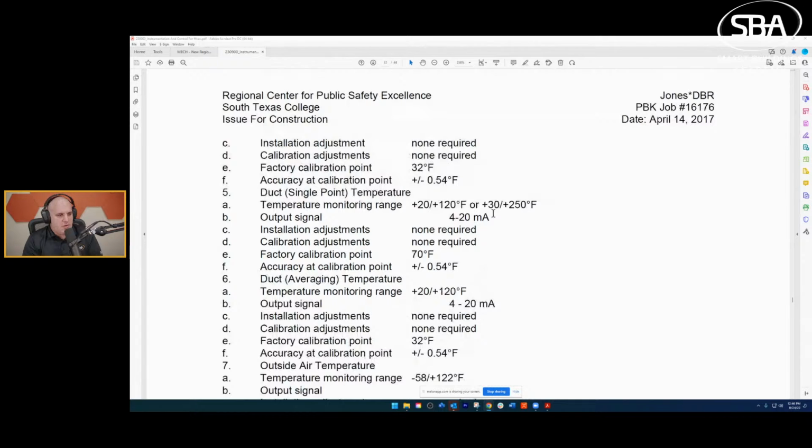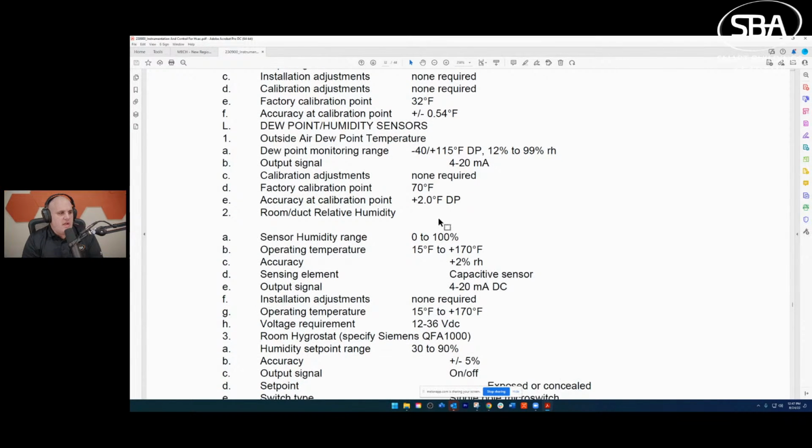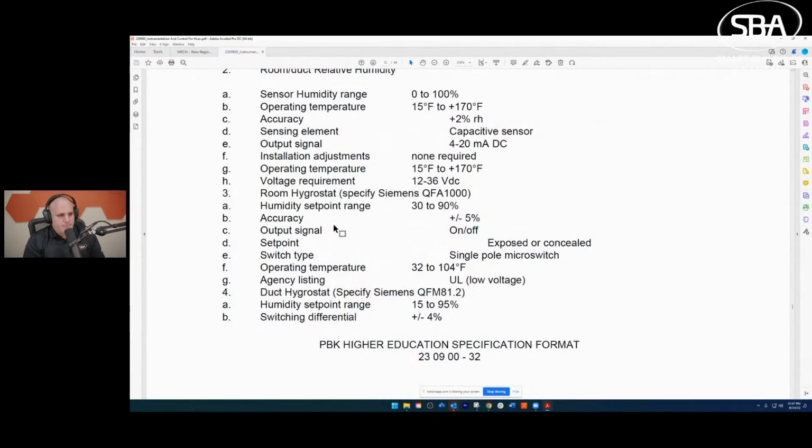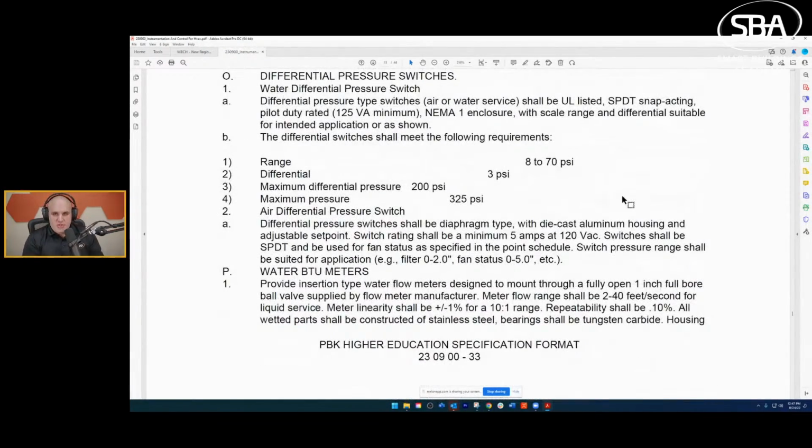So that's what I read through, right? I start to just understand. And over time, you'll start to know like, okay, this is dew point. This may be like an ACI dew point sensor, whoever, right? And then finally, once we get through here, at this point we've built out our mechanical list. We've built out our list of equipment. We've started to build out our BOM. So we've said, okay, we have zone temp, we have discharge temp, etc.